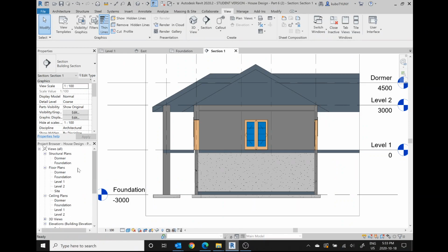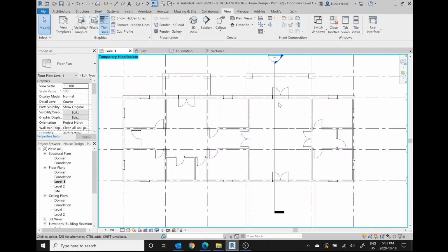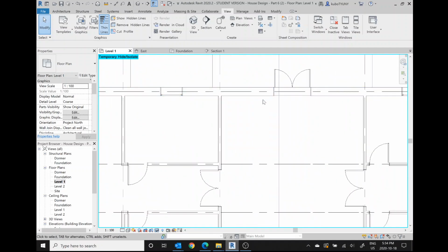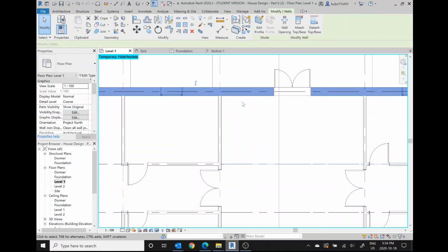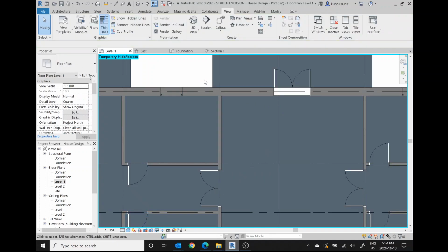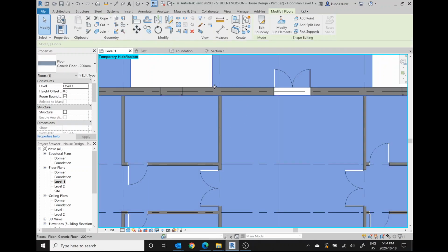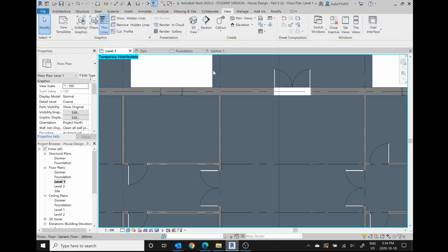So I'm going to go back to the Revit file, double click on level 1. And so to change the floor plate, the first thing I have to do is select it. And that can be a bit tricky because you've got all these walls and crazy stuff hovering over top of it. Let me see if I can give it a bit of definition here. What I could do is click over here, and I know I'll select that because here I'm picking the edge of a floor plate.